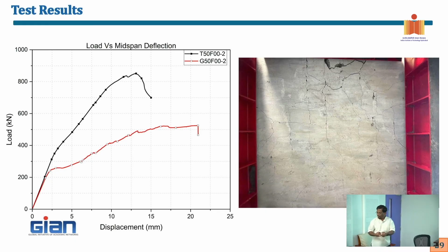Yeah, that's it. The FRP rebars are more deformable, right? And so this failed because it is able to see the overall energy absorption nearly remains same. Energy absorption is the area under this load displacement curve, right? If you equate that, both of them had nearly same area, but this had a better stiffness. That means crack widths are going to be less for a particular load.